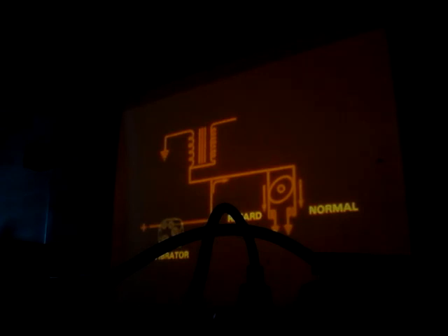It is important to remember the normal breaker points open when the piston is about 30 degrees before top center of the compression stroke, and the retard points remain closed until the piston reaches top center. And as long as either set of points is closed, the pulsating current passes to ground without accomplishing anything.